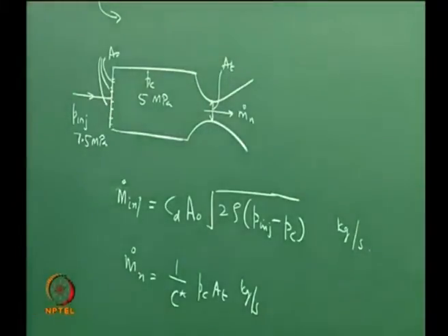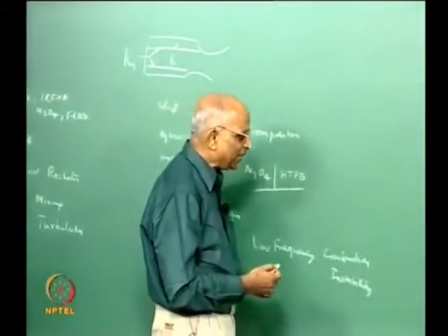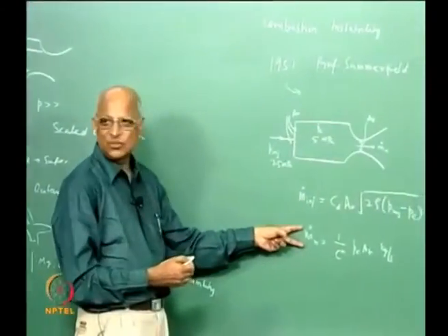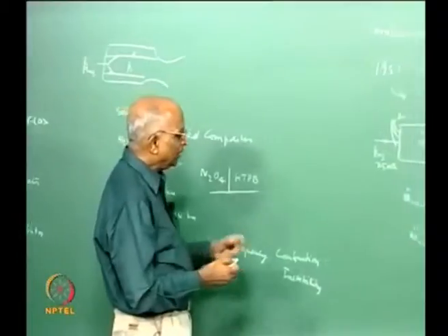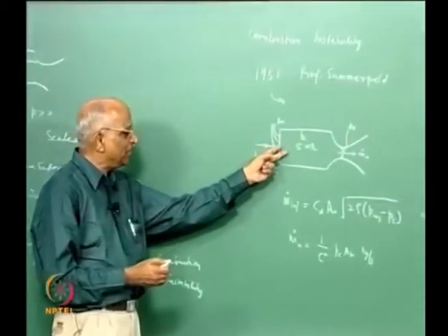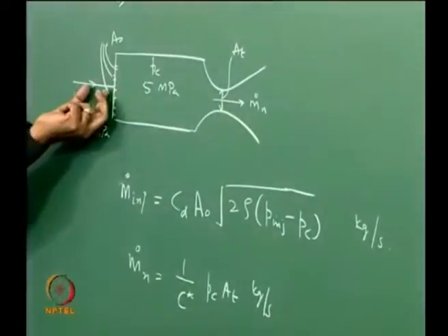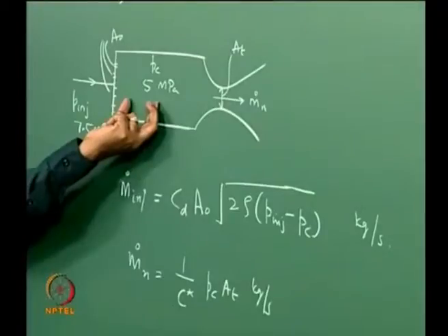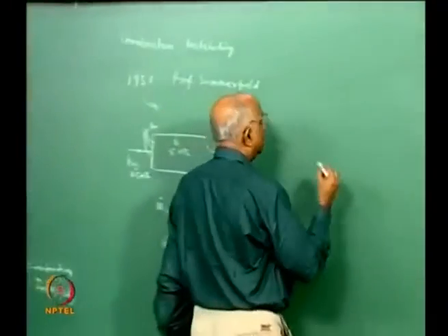Now I ask myself one question. So far what did we say? To get the equilibrium pressure, mass injected is equal to the mass which is leaving. But I have a strange problem. The fuel or propellant which is injected takes some time to burn. Suppose I inject a parcel of propellants at this rate here, it's going to start burning after some time because there has to be a delay. There has to be something like a combustion delay.